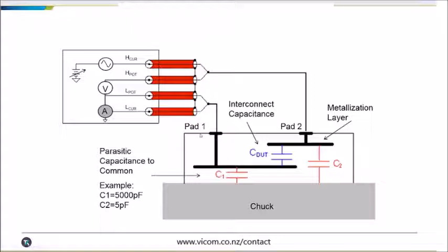So, what can you do to correct this? There are several ways, some more convenient than others. First way, you could physically switch the cabling, but that could change any compensation constants that you have set and require those compensation steps to be rerun, and the DC bias would be reversed from where you had it before. Or we could do it, what I consider the easy way, without physically changing anything.